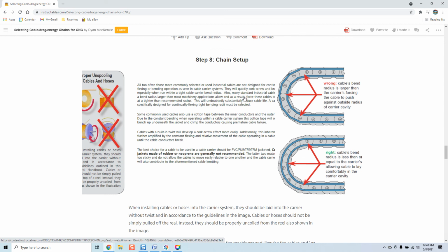In CNC use, we have different spindle cables, we have different motor cables, we have different PVCs, we have TPE, TPMs. You have all types of material used for cables, and the bottom line is this. Whatever material is used for the cable, if you mitigate the amount of friction from that cable and pay close attention to exceeding minimum bend radius, that cable will typically work fine.